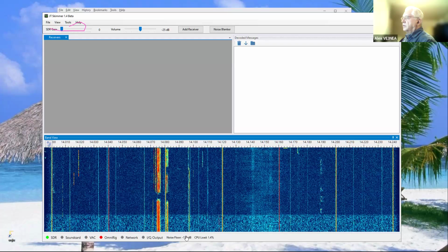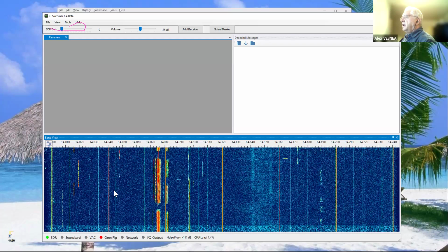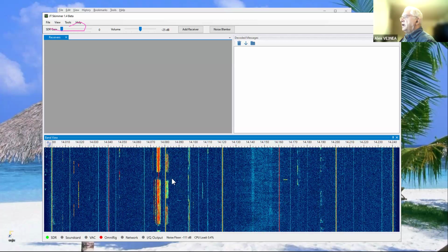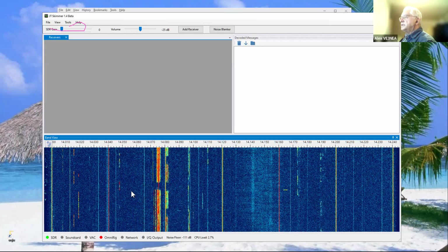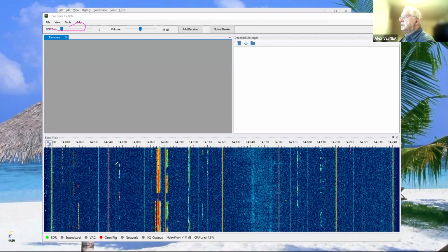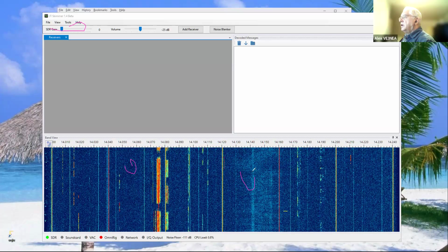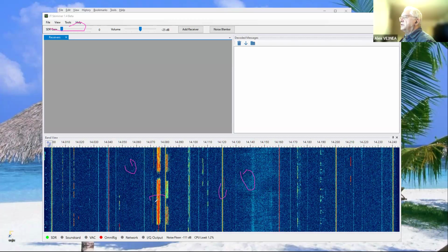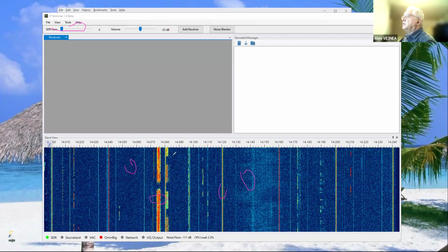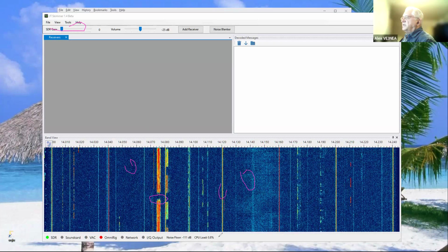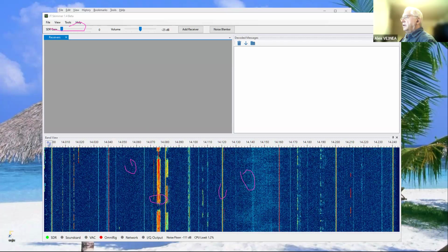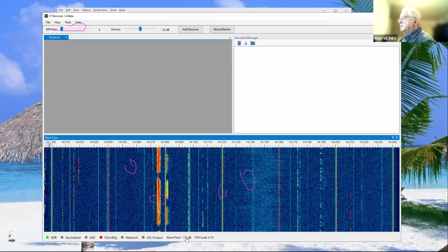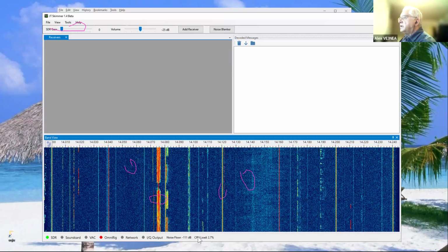Okay, noise floor. This is a display that actually processes the whole spectrum, and it looks only at the flat part of the spectrum, the wideband noise, like this, here and here, and estimates its level. The narrowband signals like this are not included in the calculation. So this is basically an indication of the receiving conditions at the moment. Initially, it's just relative to some arbitrary reference, but you can calibrate it.